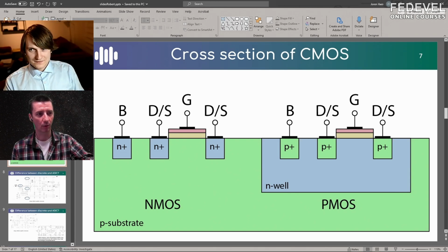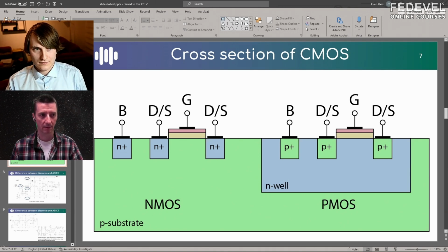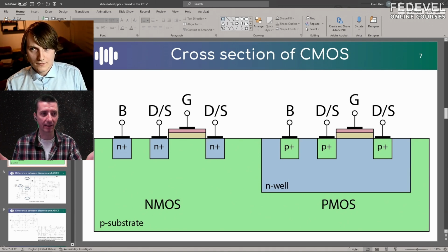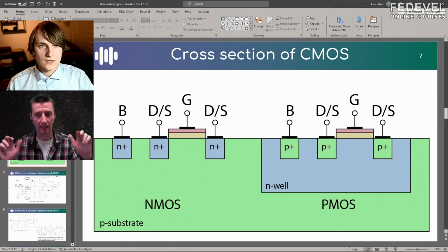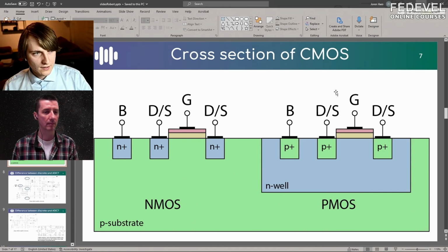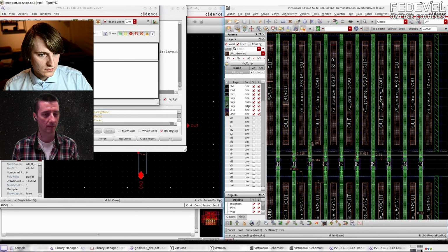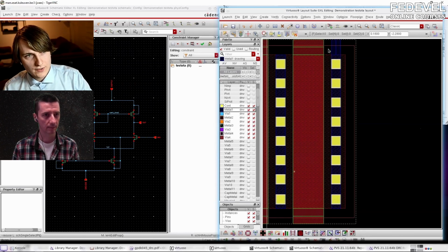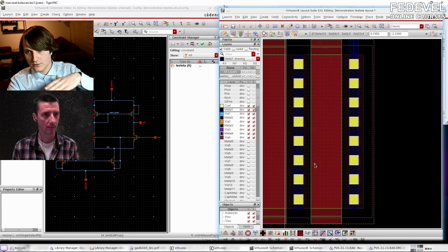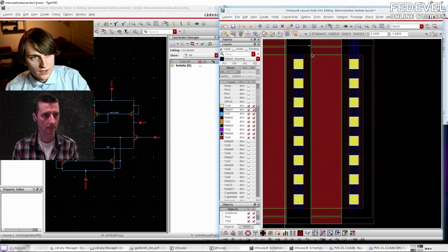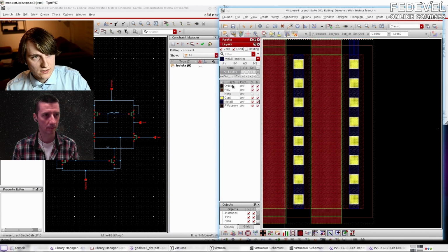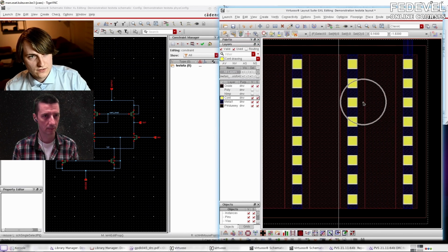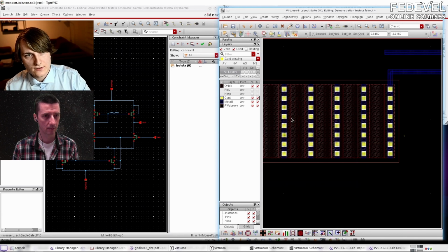Okay, and in the tool, basically, there will be all these mask layers which are applied during every single process to build this stack up. Exactly. So if you look here in the 45, this is more clear. If you remember our cross sections before, we had this gate, which is an insulator with a metal on top, so that is this red zone here. So this is the oxide, and this is the mask for the oxide. In this technology, they'll then use